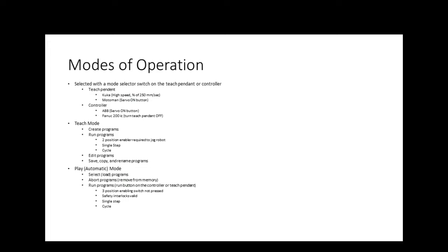Up in the top one, I didn't put it in there, but safety interlocks are what we call safeguards and e-stop, right? You understand? So e-stop is not considered what we call a safeguard. A safeguard, if you've looked at that safety lecture, which is due by when? Midnight Friday. You're supposed to watch that safety lecture to get credit for assignment 3. So we have e-stop circuits, which are your e-stop buttons or anything that, when they set up the system, they consider something that could cause injury. Then we have safeguard circuits, which only come into play when the robot's in automatic mode.